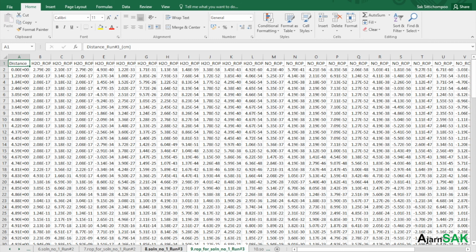When you increase your temperature to 600, this is not the case anymore, and it's shifted to another reaction. Reaction number 3, for example, would be the most responsible for NOx production. So you can have very good ideas of what's happening in experiments, for example why NOx is dropping. You can know from here, and we know the mechanism that is responsible for that. This will also help you very much in analyzing your experimental results.